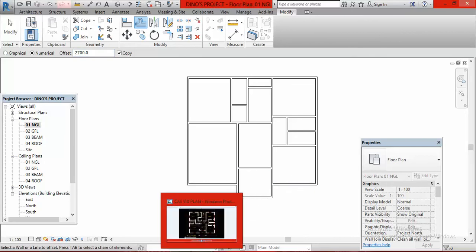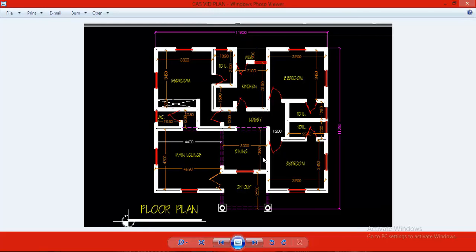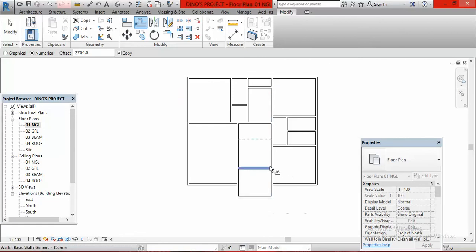Let's see my dining. I go to the dining. The dining height, vertical dimension is what? It is 2850. 2850 plus 150. That is 3000, right? Yeah. Add it. It should be 3000 now. Okay. So I click on Revit again. I go to offset. I make this one 3000. Then I come to offset it. When I offset it, it will give me this wall. Then I press escape twice to end the command.